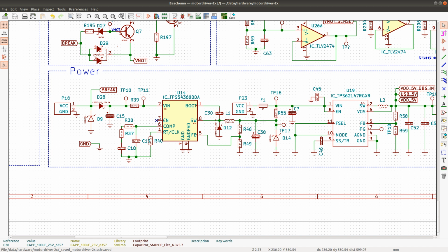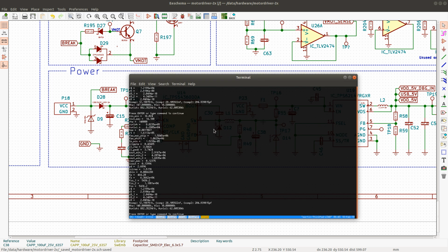But that's not a big difference, and usually 12 volt circuits can accept 14 volts because they're created for automotive applications where you have 12 volt supplies, and in the car the voltage can easily rise to 14-15 volts when the car is running.